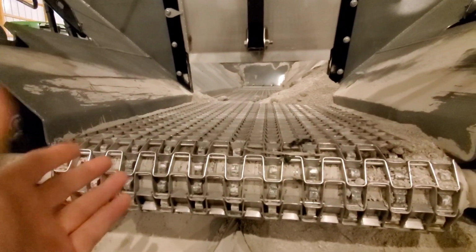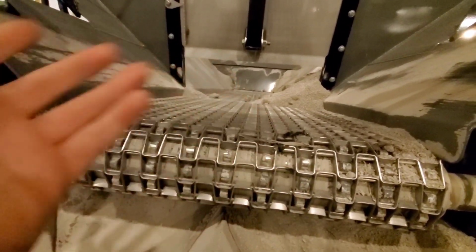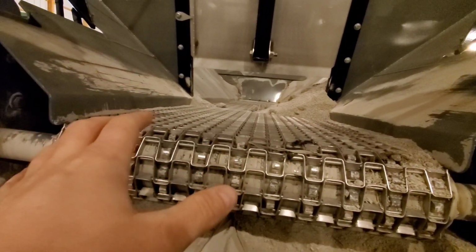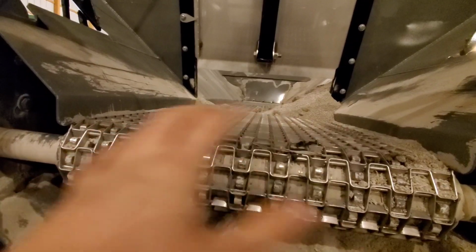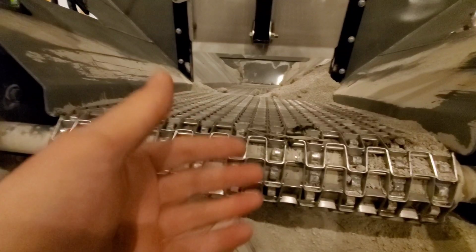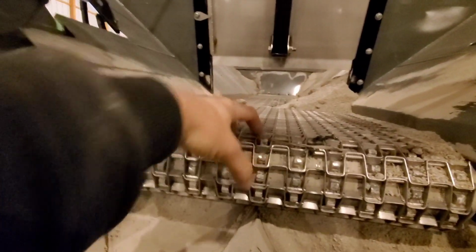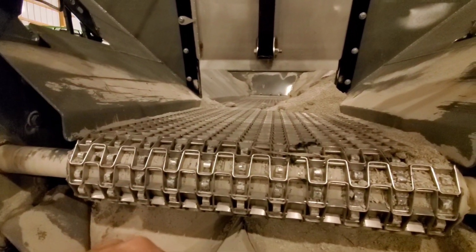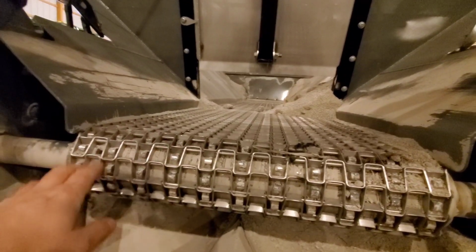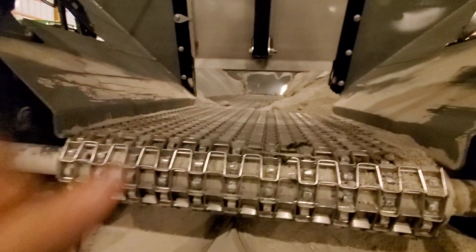I was also asked about this chain, and several guys had some concerns, several guys liked it. The chain is going to be your best bet for fertilizer and lime, period. Even a belt over top of a chain, when you get lime sticking in the box, this will chew on it like a cheese grater, whereas a belt can slip on it. So in my opinion, this is the way to roll. And this is very precision for fertilizer because each little bit of fertilizer sits in these pockets instead of just having a big bar.